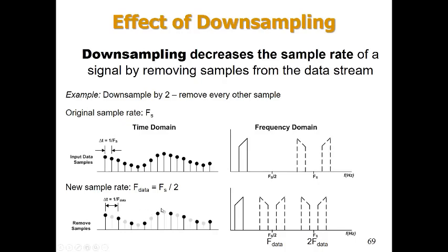Now what's happening in the frequency domain is, obviously, when we go from one sampling regime to another, we're changing the sampling rate. In this case, we'd be cutting it in half if we threw away every other sample. In the analog frequency domain, we have our original signal and its negative version over here. And we've been making copies of that combination centered on every integer multiple of the original sampling frequency, fs, which is 1 over the time shift between these two samples.